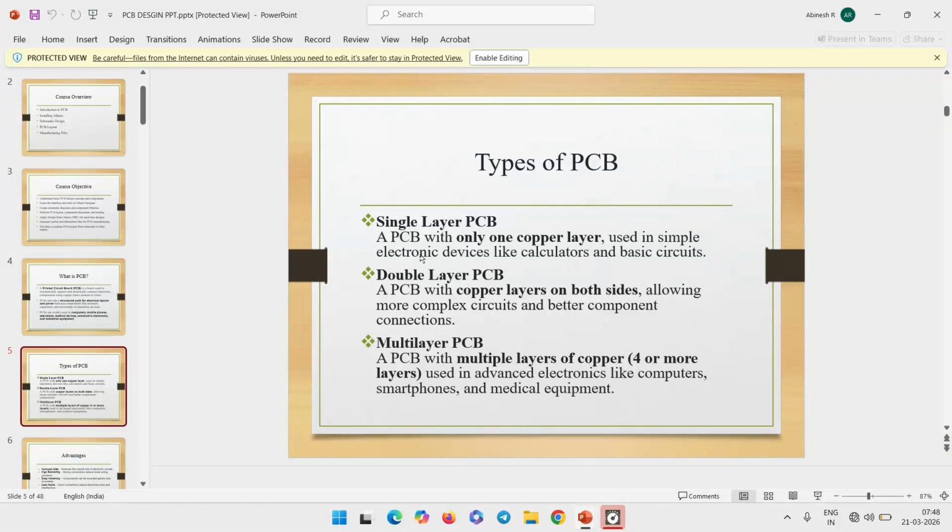The vias are nothing but a vertical interconnect access. The guys who know about it will know that a via connects the top and bottom layers. A via is a hole which is drilled and electroplated. Electroplated means it is able to carry a signal or current from the top layer to the bottom layer. Okay, this is the purpose.